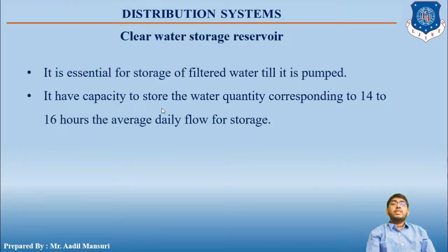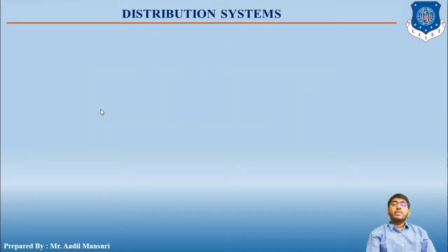It means that we all know that out of the 24 hours, the water has to be pumped into the community for 14 to 16 hours. Okay, and these storage reservoirs have the capacity to store the quantity of water which has to be supplied in these 14 to 16 hours. Okay, so let us move ahead.